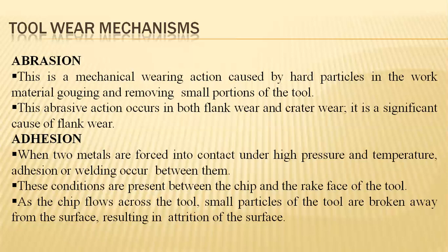Hence, this will result in the deviation or removal of small portions of the tool also. That particular abrasion, that is called abrasion, will be getting elevated from the tool in the form of an amorphous state, a light powder state. At that particular region, both the flank wear and crater wear will be coming into the picture, and this flank wear is due to the abrasion.